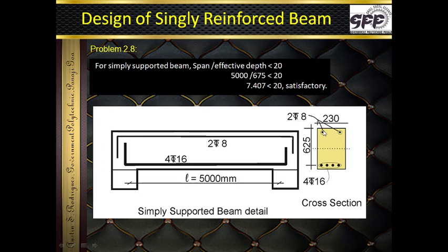Now these 2 hanger bars will have a round bar going around the periphery like this, and these 4 bars will be sitting on the round bar, a bar which will be going all around this. So these bars will be sitting on that. This all-round bar makes these bars, this Ast, hang over this portion. Now notice this portion over here, from the bottom of this to here, is the clear cover.